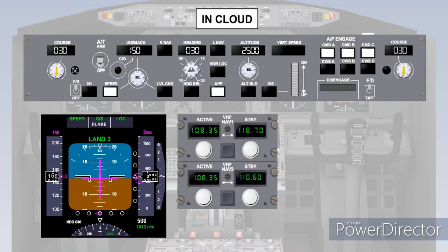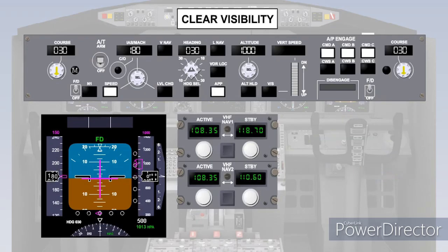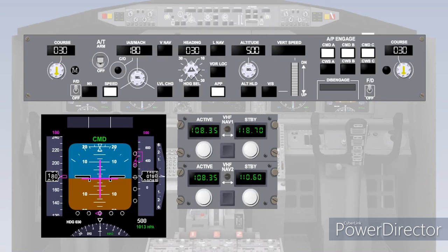The alert height is a specific radio height, which is based on characteristics of the aircraft and its fail operational landing system. In simple terms, this means that should a failure occur of a required system above the alert height, the approach will be discontinued and a go-around executed. This is unless reversion to a higher decision height is possible, and decision height will be defined in the next scene. If a failure occurred below the alert height, it would be ignored, and the approach continued to complete the autoland.